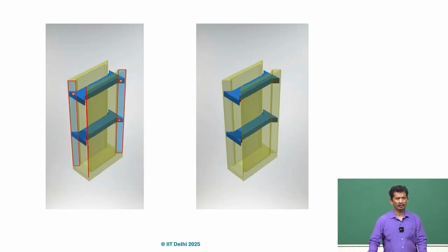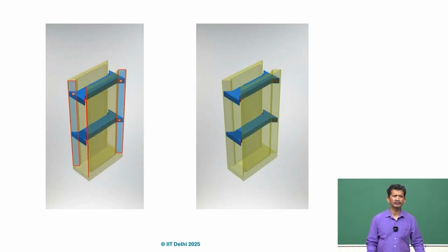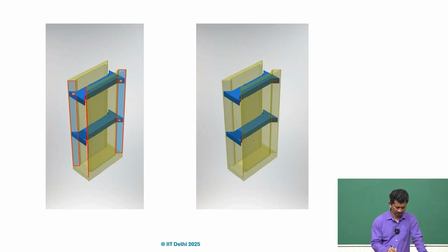What we did here in this case is we just tried to define those 5 contacts. We developed one model in one of the CAD packages, and what we see here is that with the 5 contacts we can just animate it, and you do not depend on the tolerances of individual parts. What is the angle of the V grooves, how flat is flat, what is the location of those. If it is slightly off, it does not matter. So it provides 5 constraints and 1 degree of freedom, which is this one.